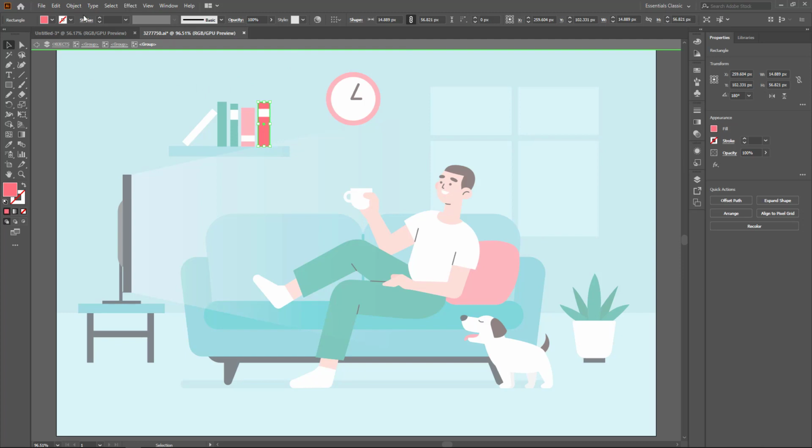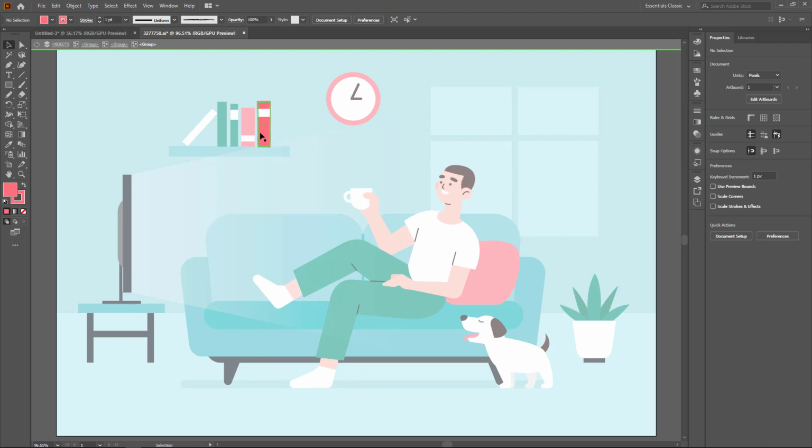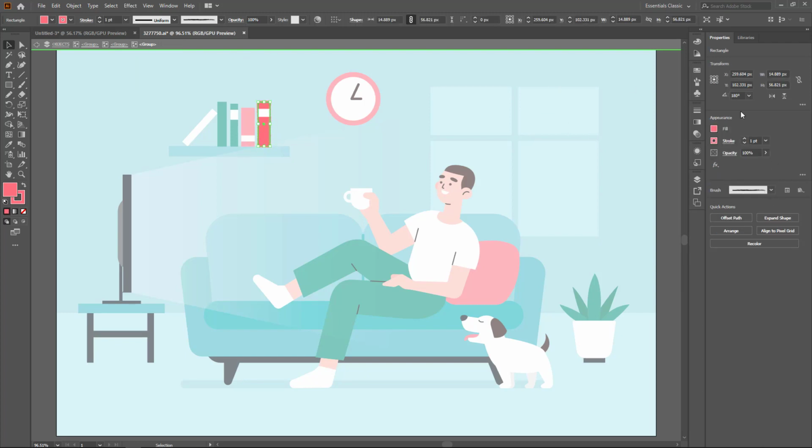First of all, the properties of the object that I have selected show up on the top and on the side. These are duplicate properties, but this top properties bar has a few more quick launch options. For example, if I wanted to change the stroke of the object, I could come in here, click on this down arrow, and very quickly choose a different type of brush for the object. How often do you do that? Well, not very often, but I could easily do that in the properties menu on the side. The same options show up here just to let you know that they're duplicate.